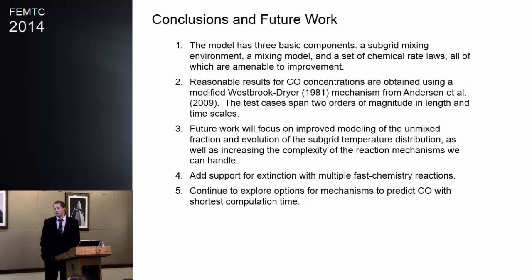One of the things we want to do is look at transporting that zeta term, that unmixed fraction. Right now, at the start of every time step, we assume zeta is unmixed and allow it to mix based on the turbulence. But we realize that once it's mixed, it's not going to unmix. And so that means we have to transport zeta. Zeta is a non-conserved passive scalar, so it doesn't impact the flow field. So it is something we could transport, but we don't really have the mechanism in place. That's something that Randy and I are going to be working on sometime soon, hopefully, in order to be able to transport zeta.